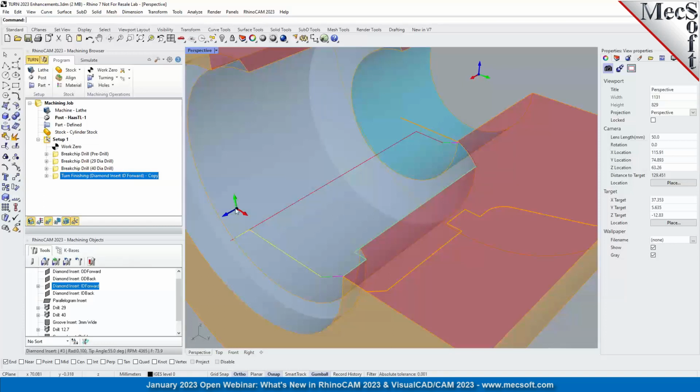And then if you had an operation after that, since we don't insert any motions between operations, it's going to take off from wherever the tool was and go to the start of the next operation. And that ended up, in most cases, as a diagonal cutting into the part. So what we do now is we retract to this safe clearance plane, so that will never happen. It'll always go back to the clearance plane before it starts the next cut.